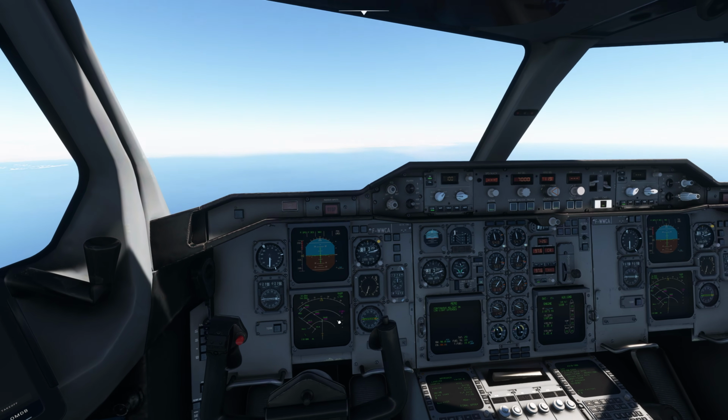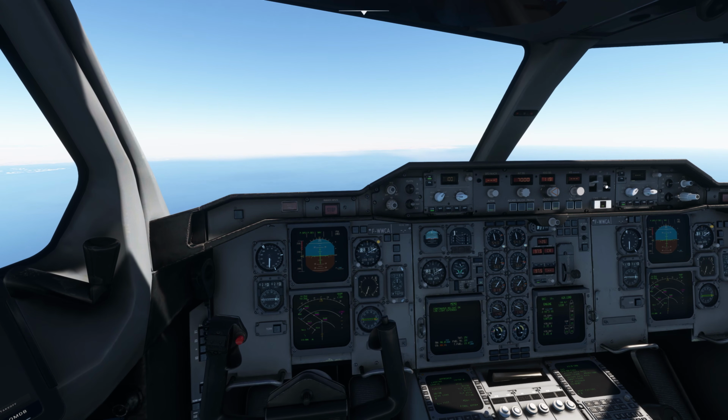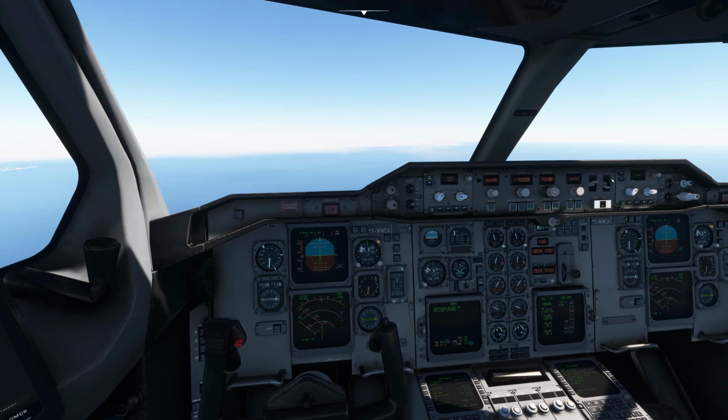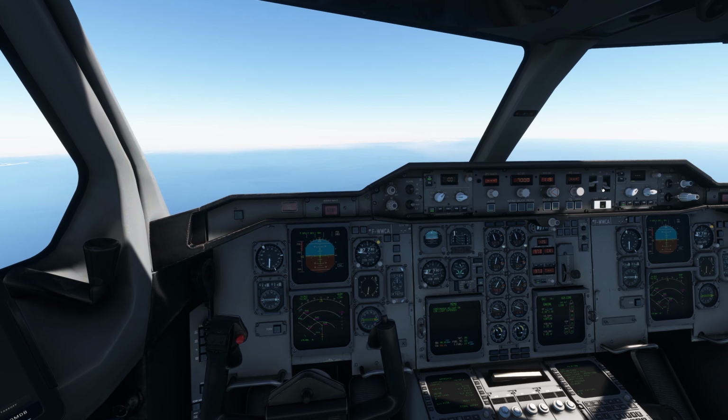This plane is capable of carrying a Category 3 approach and auto land as well. You can press this button, and it can perform a Category 3 approach and then auto land as well. I have done this 2 times, but it's not that accurate. So for this video, I will deactivate the autopilot. Now I will not turn on this option to have a category 3 landing. So I'll just go with the category 2 because at category 3 you can set the minimums at 50 feet. Why do you set the minimums?